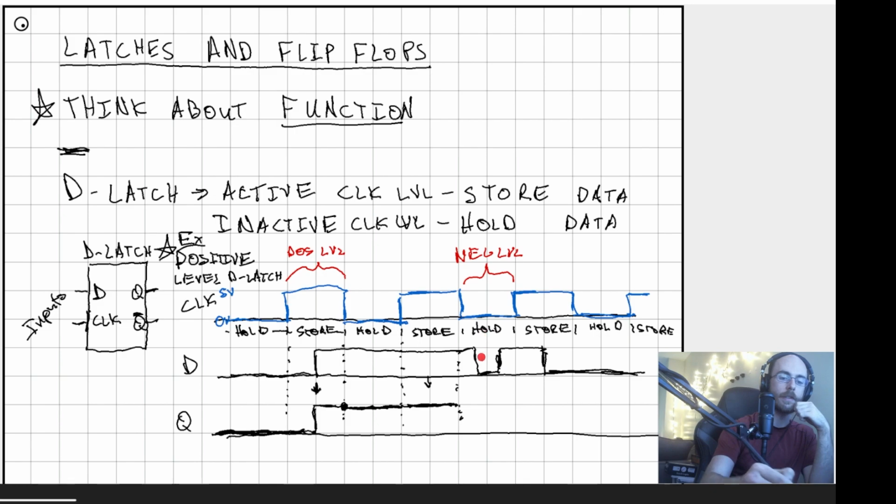Now the next step, this is why I wanted to be a little tricky with you guys. What you see here is we're holding, which means we don't care about what's happening here with D, because all we do is hold whatever value Q is and hold it across. Notice how we're skipping over this little divot in D where it goes down and back up, because all of it happens during the hold. The hold holds the Q value. It doesn't care about what D is anymore.